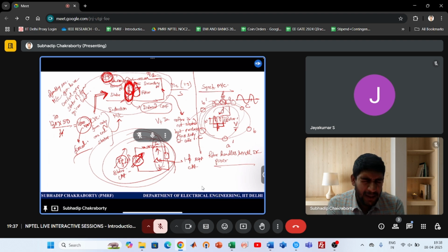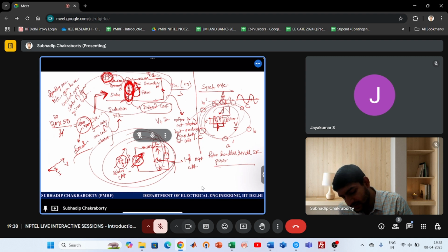So I want to transmit the power, but at a better power factor. Why are we always concerned about better power factor? Because for a better power factor, you can transmit the same amount of power for a lesser amount of current. Why, you know? See, this is voltage, this is current, and that will result in some power, right? So the in-phase component of I can be thought of as delivering the active component of power.